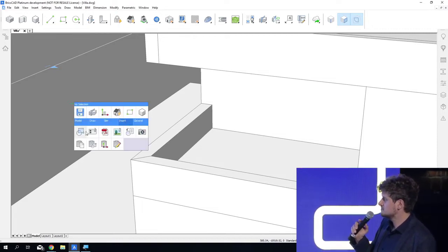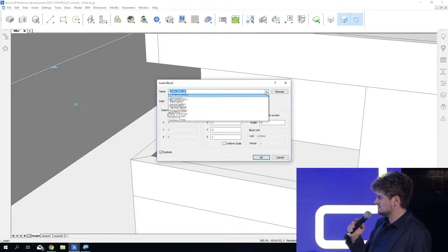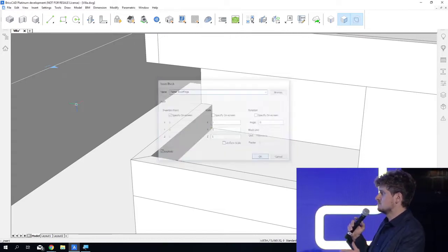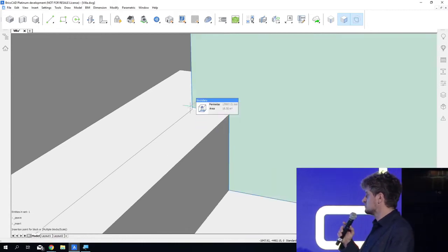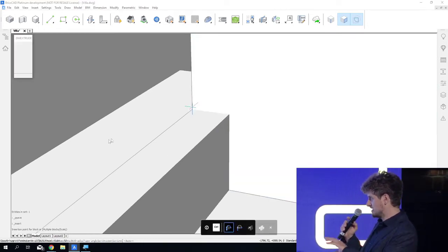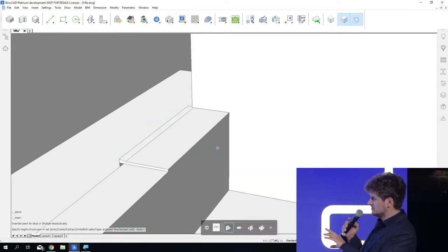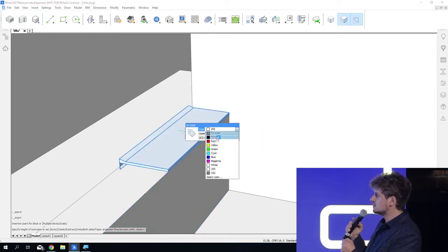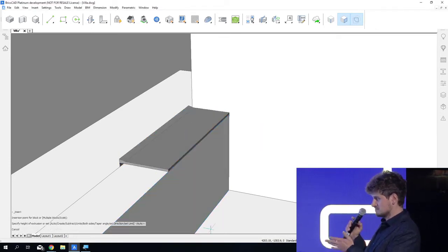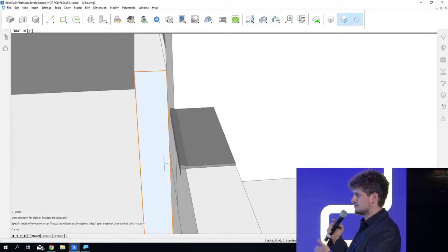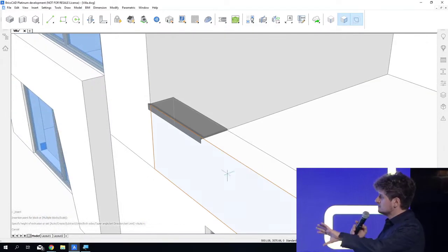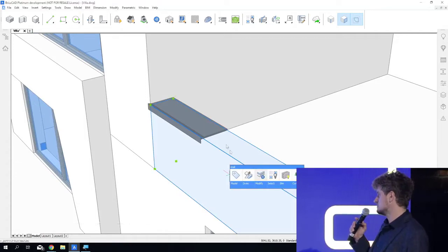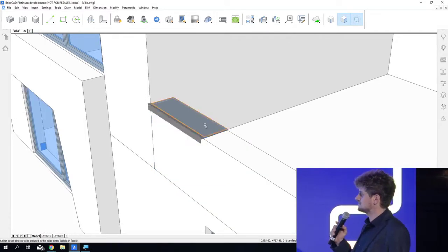The next application we will show is adding a wall cap to these little railing walls. That's with another specialization of this propagation tool, where we propagate along an edge. Here you just start with a small wall cap, just design it from scratch or you import it somewhere. And now you can propagate it all along the edges of these similar surfaces.